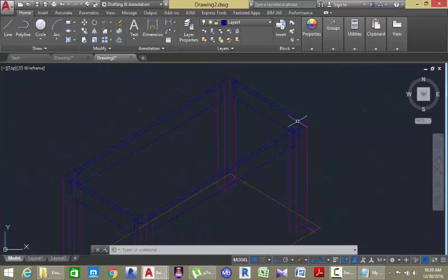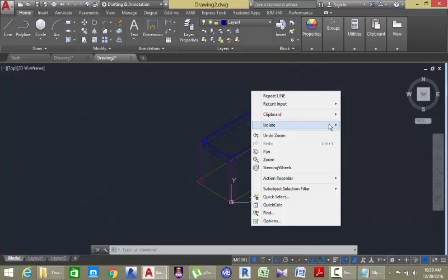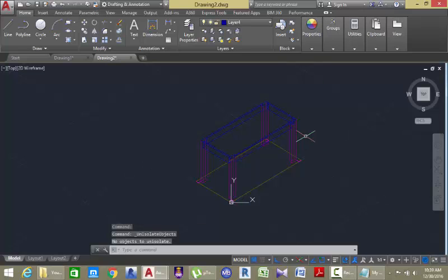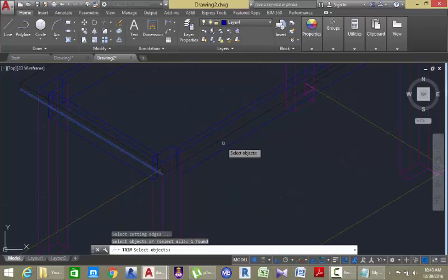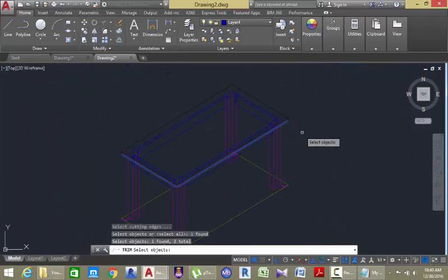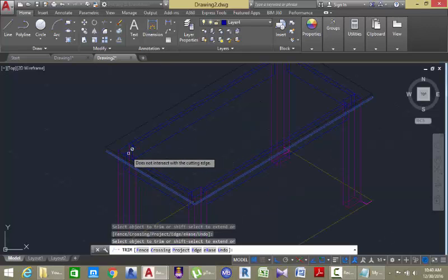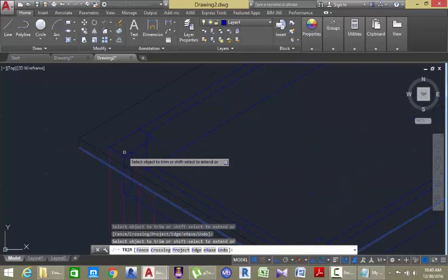We need to eliminate some of the excess lines. Now right click on the drawing area and select end object isolation. Go to the layer panel and click the third layer button. This will bring back the tabletop. So any object that you see through the tabletop needs to be erased, because in the real world this is not going to happen. Go to the Home tab, modify panel and select the trim command. Select this line, press enter. Try to erase this excess object.